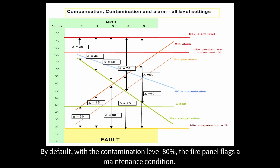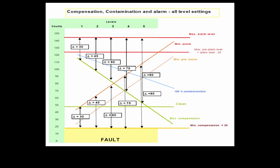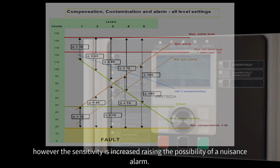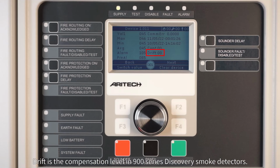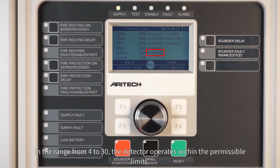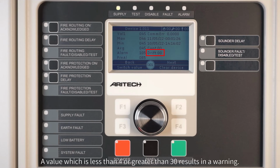By default, with the contamination level at 80%, the fire panel flags a maintenance condition. The sensor is still able to indicate smoke, however the sensitivity is increased, raising the possibility of a nuisance alarm. Drift is the compensation level in 900 series Discovery smoke detectors. The compensation algorithm is done by the detector itself and stored as a single value between 0 and 31. In the range from 4 to 30, the detector operates within the permissible limits. A value which is less than 4 or greater than 30 results in a warning.